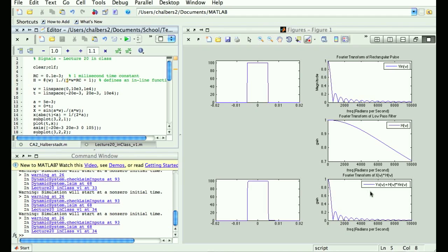Yes? How come the previous graph for gain, this one looks like it has the 20 dB per decade slope? It's only because it rescaled the y-axis. Before it was from 0 to 1, now it's from 0.7 to 1. You just zoomed in on a little piece of it.